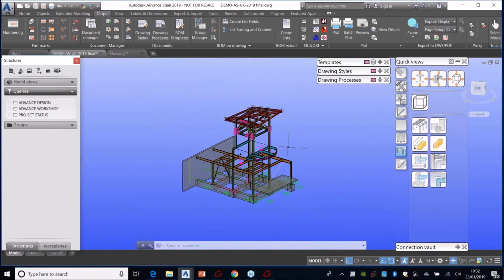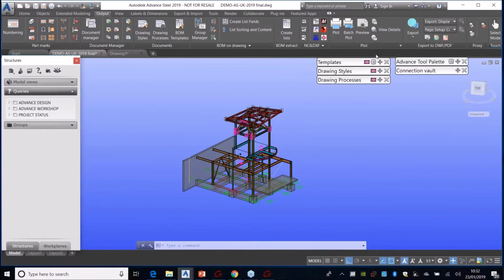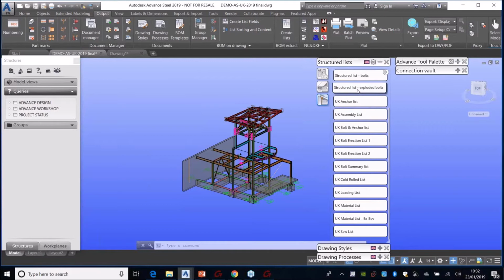Now, we also mentioned that we would want to build filters or queries with the Explorer. Why you'd want to do this is just to facilitate extraction of any sort of list that you're sending to a fabricator. For example, if you're outsourcing just the plates, you don't have a plasma machine in-house, and for the beams, depending on the sizes of projects you take on, of course, maybe those are just being burned manually in terms of copes and holes associated to the linear items. So then maybe you want to build filters.